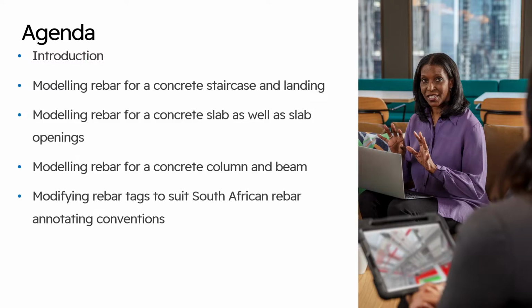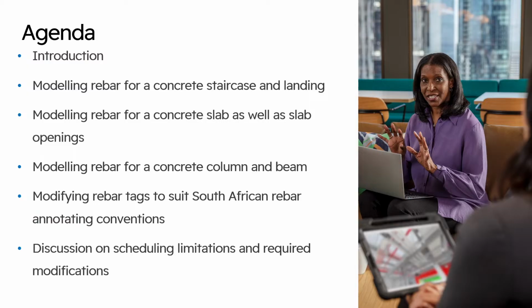And then we'll look at modifying rebar tags to suit the South African rebar annotating conventions, which I think is quite an important one. If anything limits us from adopting just 3D rebar detailing, it definitely is when it comes to the annotating of rebar in the Revit space. And then lastly, we'll have a short discussion on scheduling limitations and the required modifications.